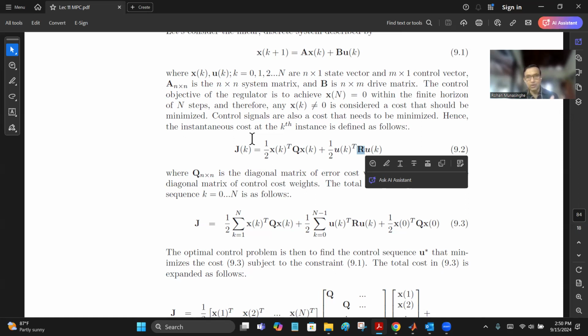If you think of a moving vehicle, maybe you want to give higher priority to position, maybe lower priority to acceleration. So this Q allows you to set these values. In the MATLAB codes I shared with you, you will see the Q matrix, a diagonal matrix, with different numbers there, which means I have given different emphasis and importance to different state values. Same story with the matrix R.